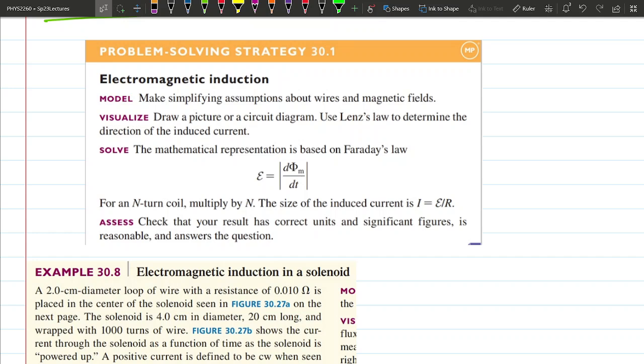In our case, it's x times L times B. You want to take a time derivative of it, and be careful which thing depends on time. In our previous case, x is the only thing that depends on time. In the future, it could be y, or it could be the velocity that depends on time also. That will allow you to calculate the induced voltage on that loop.